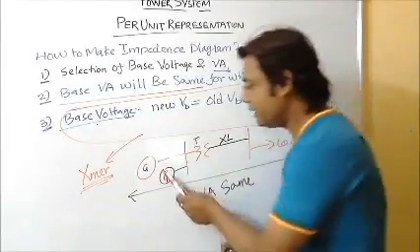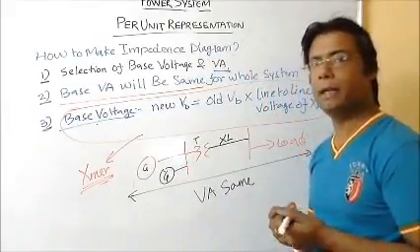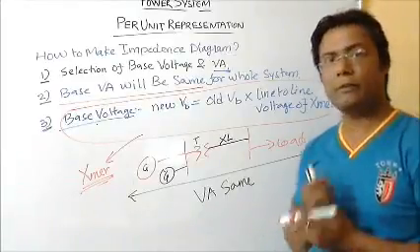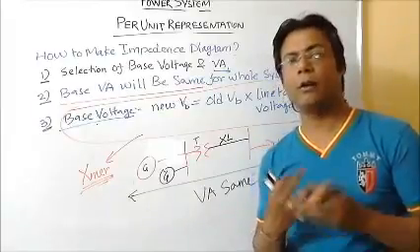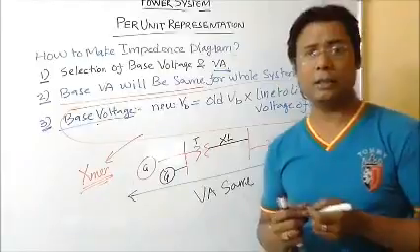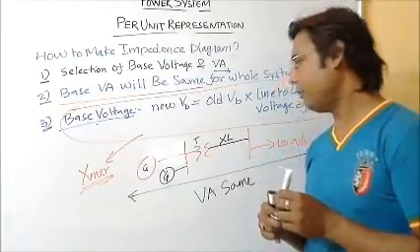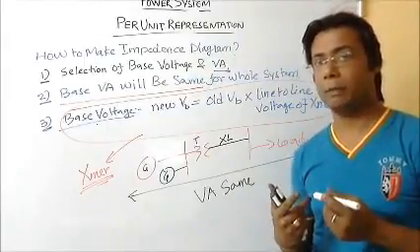When I convert this into the reactances, or impedances, that will be an impedance diagram. The impedance of everything is collectively drawn in the same place, and that is called the impedance diagram. We know all these things, so not to go into that deeply. But the thing which is very important here is understanding the change of base from one place to another.